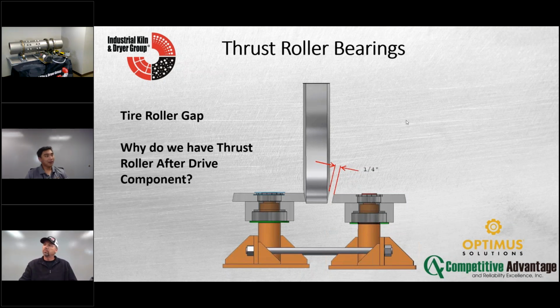If you want no gap, your unit is not, quote unquote, floating. You're trapping it. Some of the groups we worked with say, hey, this unit is doing great, and you say, it's not moving, and both the thrust rollers are rotating. That's one of the effects of trapping a unit. You can break the thrust roller, and you put grooves in it. If you trap it and it can't move, you get grooves.